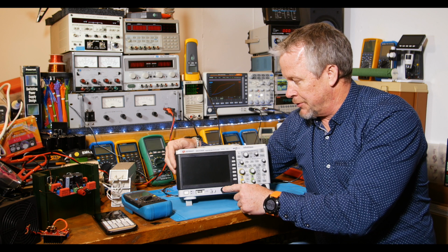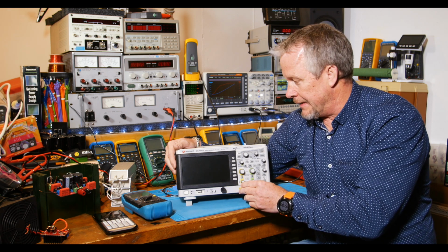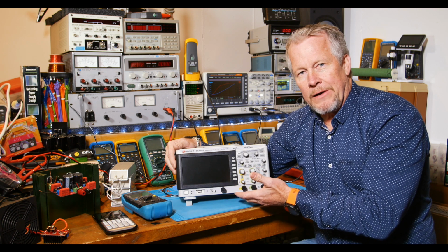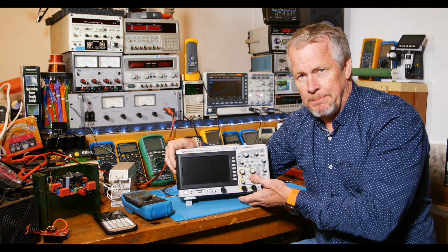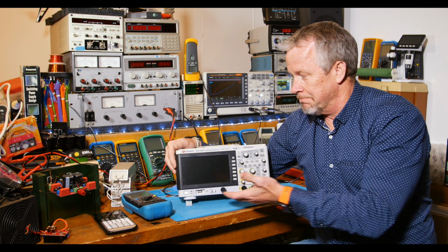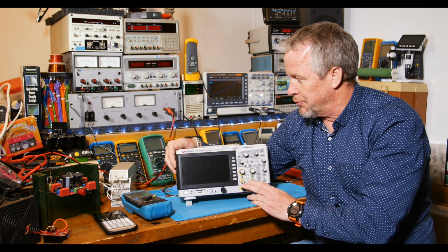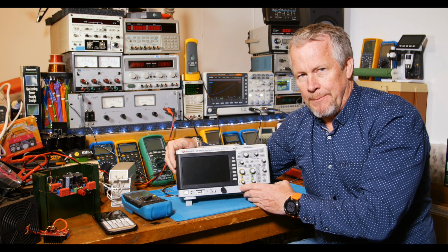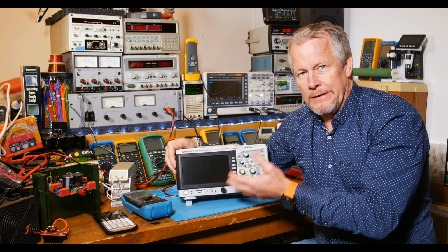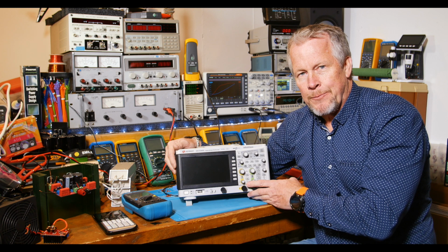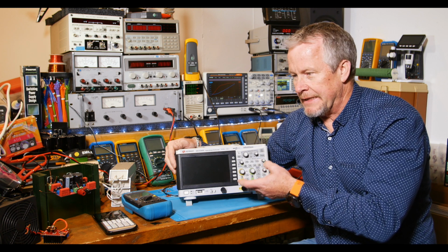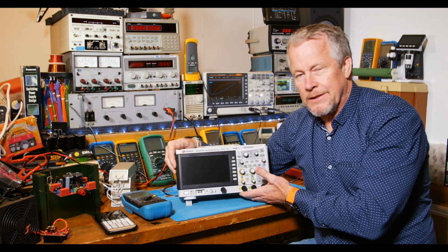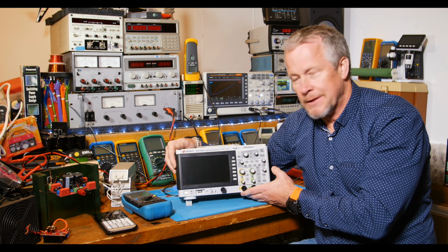So as the scope's doing that, it's taking readings on channel 1 and 2, and it can do FRA analysis, frequency response analysis, which provides a Bode plot, which is really cool, very useful for a lot of things. If you're doing amplifiers, it can give you gain and phase of your amplifier. Speaker crossover designs, it can give you the same kind of thing: your gain, phase, and impedance of your crossovers.